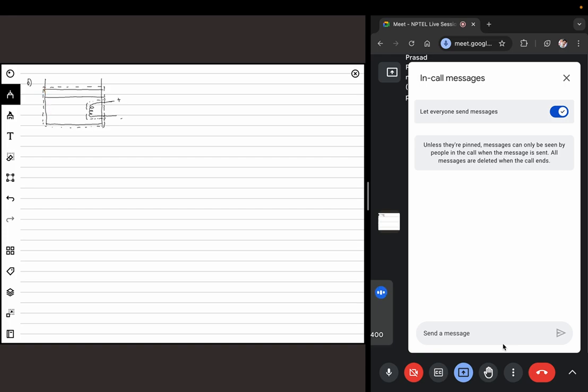So now let's write the first law. You have del Q equals del W plus dU, but now my system has air plus piston. The piston mass is not changing, air mass is not changing, so I can consider that as a system. I think there are no questions in that part. Coming back here, del Q will depend upon the total number of interactions that you are having. If you see all the interactions, you should count one by one at the boundaries. The first interaction at the boundary is between the resistor and the air, so I'm writing it as del Q, resistor and air.